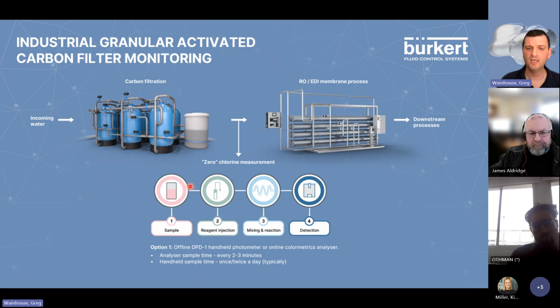So this is where we haven't got issues with pH drift or electrolyte drift. You're using a colorimetric solution, but then you've got the T90 time of it taking the sample every 2 to 3 minutes, or even longer if you're trying to conserve the reagent. So it's not something, again, we would recommend, but it's the best of a worst case scenario,